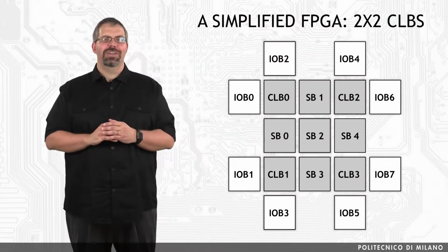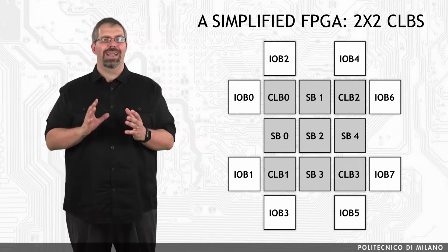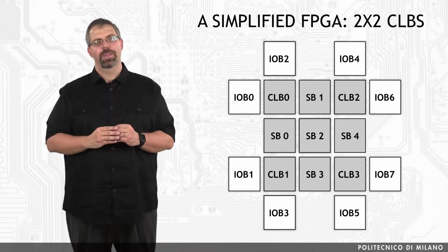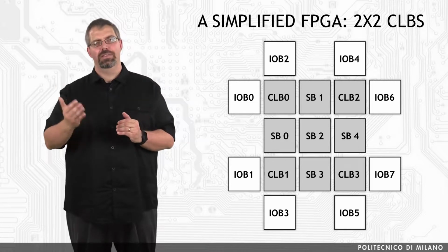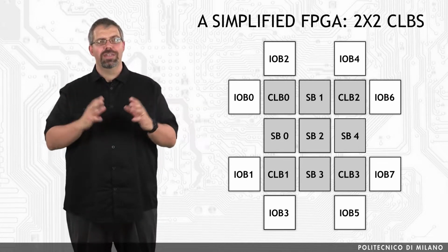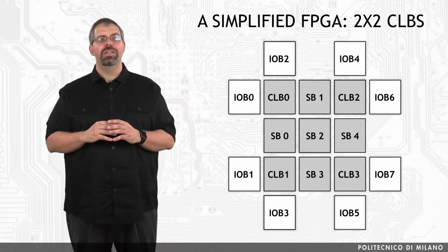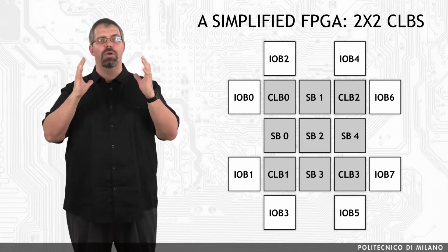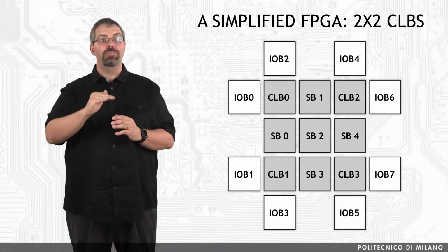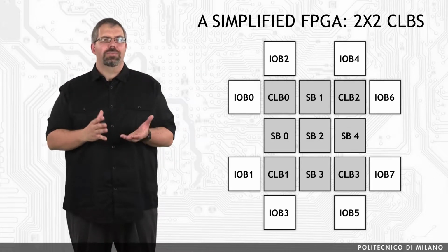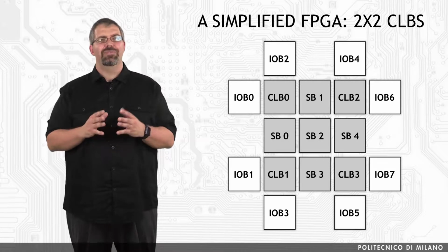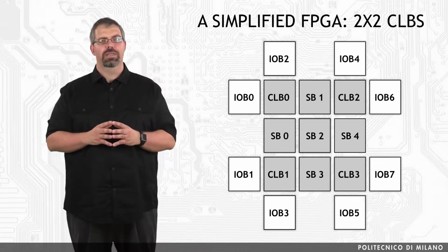Let us now consider an example to better clarify how the interconnections are working. The three building blocks presented so far, CLBs, IOBs, and interconnections, interconnect together in the device to create a communication infrastructure composed of the communication lines and IOBs around a two-dimensional array of CLBs, which covers most of the available die area and represents the true FPGA building block.